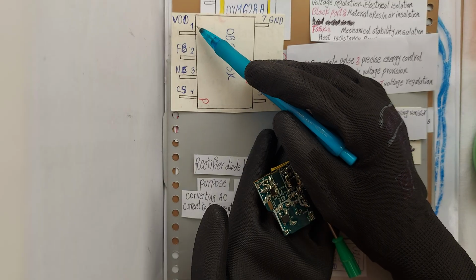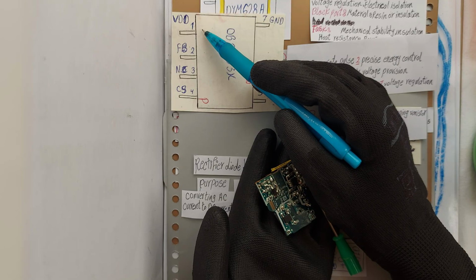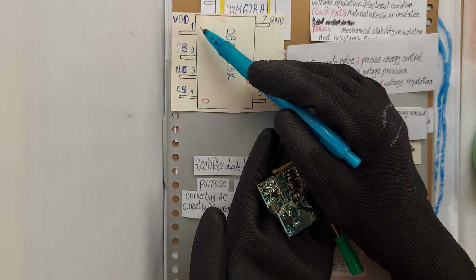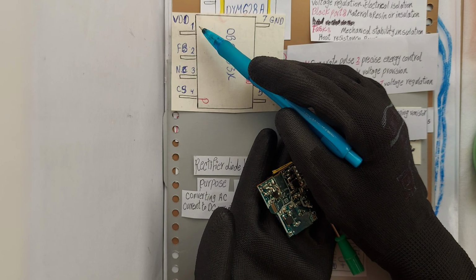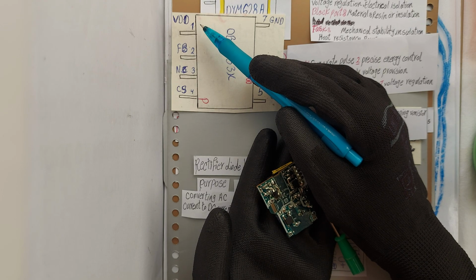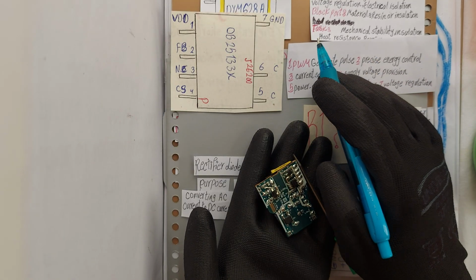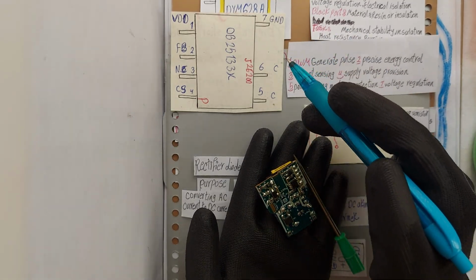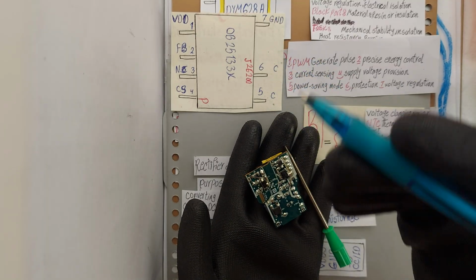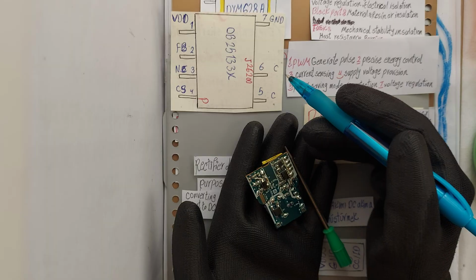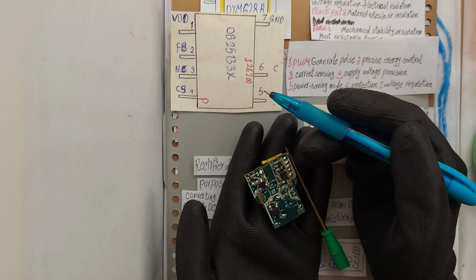At startup, when the IC isn't yet active, a resistor from the DC bus, called the startup resistor, trickle charges the VDD capacitor. Once the voltage reaches a sufficient level, the IC turns on. After that, the IC's power no longer comes from this resistor, but from the transformer's auxiliary winding, or AUX. AUX stands for auxiliary, meaning helper. This winding acts like an internal charger supplying the IC's required voltage from the transformer.